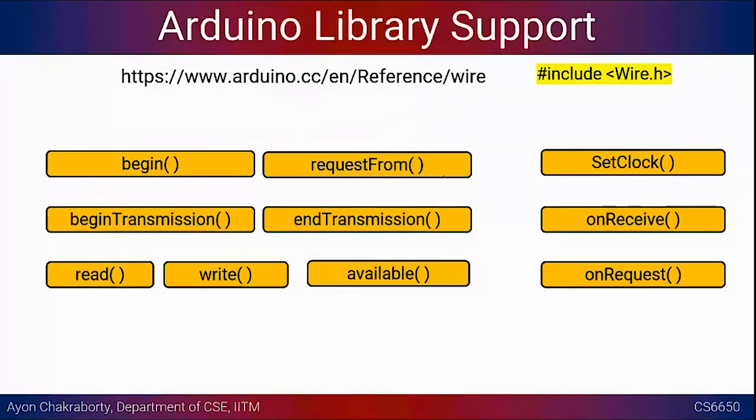If you have time, look at one or two of these implementations, and how Wire.h takes help of the TWI interface, and then the TWI interface has the implementation. So Wire.h is something like a wrapper for the I2C interface, which has some extra functionalities that the native TWI interface might not have.